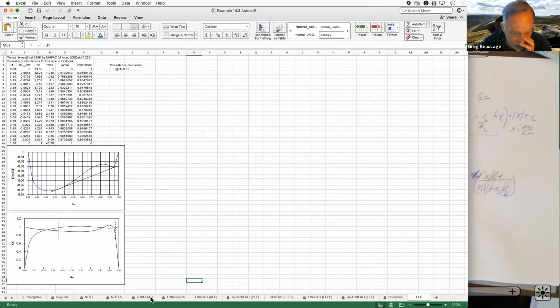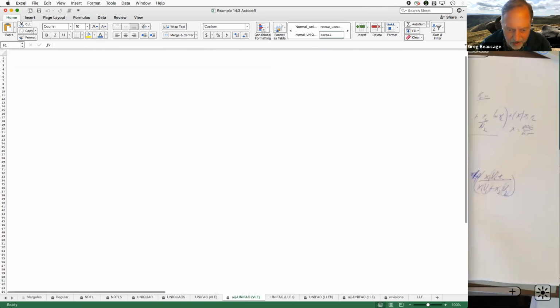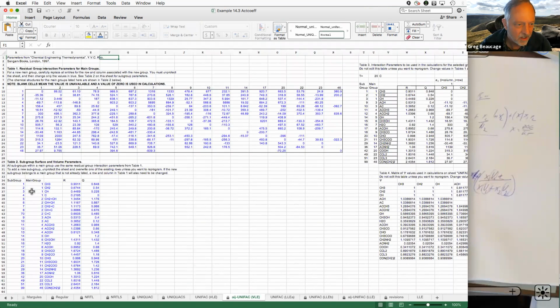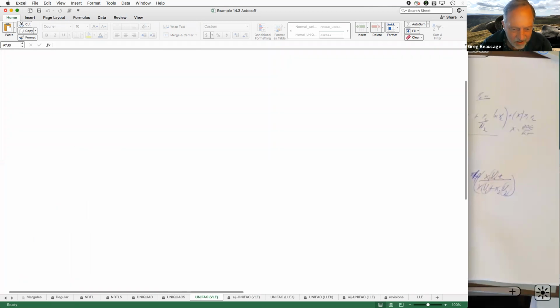So if I go to like UNIFAC, right? So it's vapor, liquid, liquid, liquid, but it'll ask me which chemical groups do I have? Okay, so like here's the subgroups and the numbers, right? Oh, this is just the UNIFAC table of the values, right? And if I do like UNIFAC, that's the AIJ numbers. And then this is UNIFAC VLE. This will have you put in those numbers.